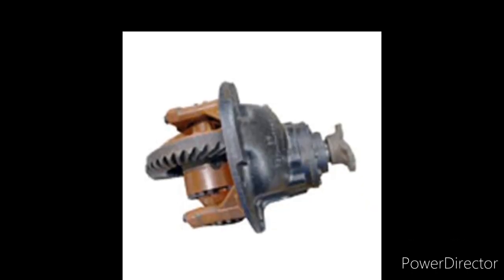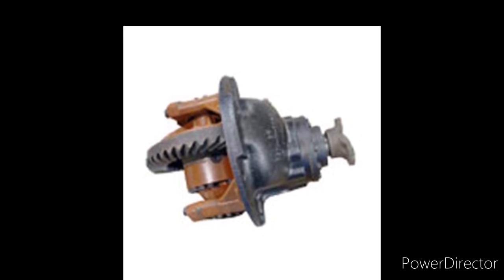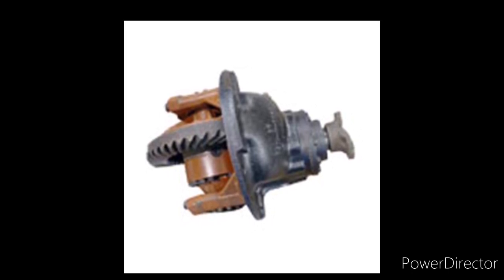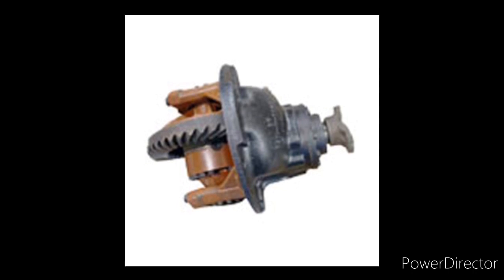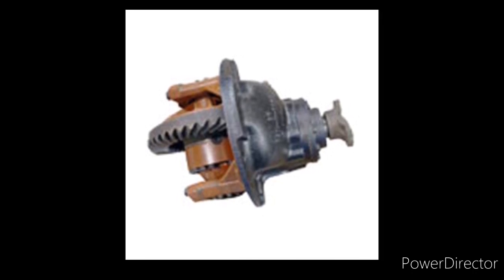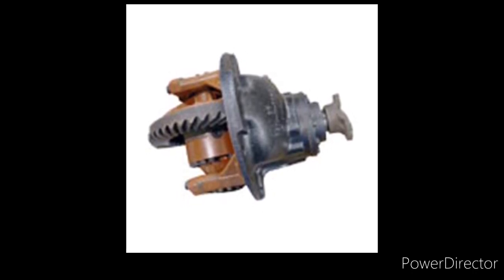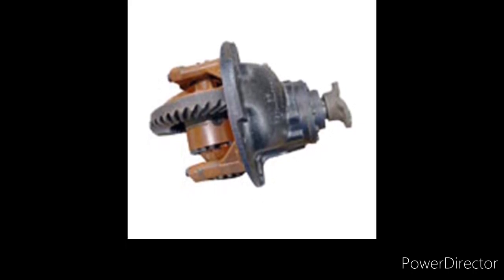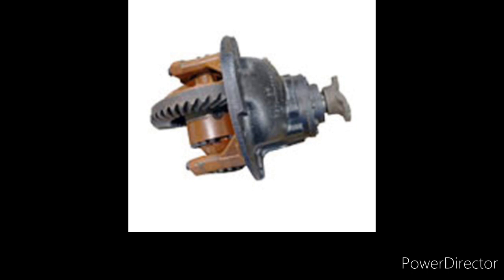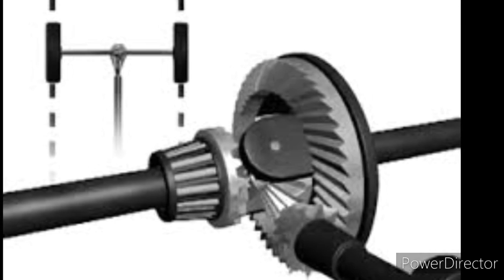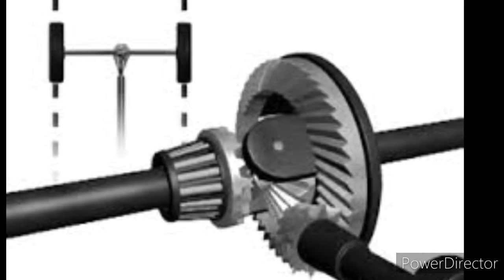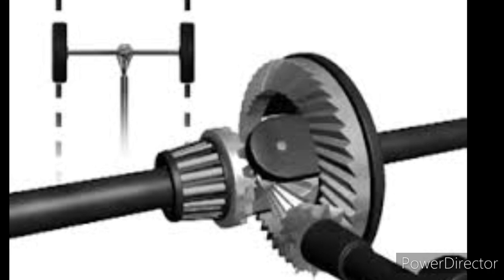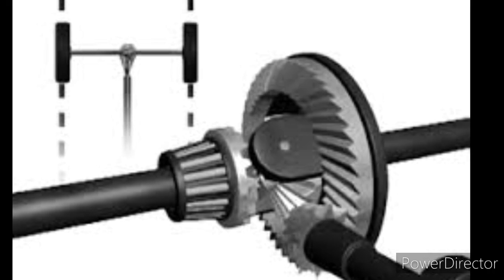Forklift differential. An assembly that is found in the drive axles of both electric and IC forklifts is the differential. The differential is a cluster of gears designed and assembled so that it allows one wheel to rotate faster than the other. This is necessary because when turning, the inside wheels do not have to travel as far as the outside wheels. The outer wheels must turn faster to keep up during the turn.